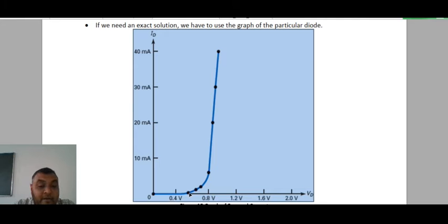Then after that, when you are increasing the voltage, you can see over here at this line that a small amount of current is flowing in that particular condition. And this third point, it is first when the current starts increasing slowly, then second, and then third point. This third point is approximately about 0.7 volt. Okay, so that is the 0.7 volt you can see over here.